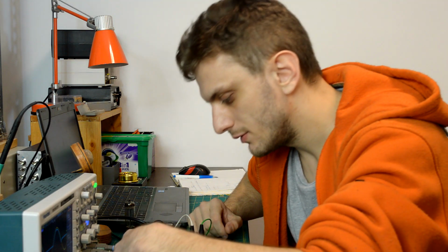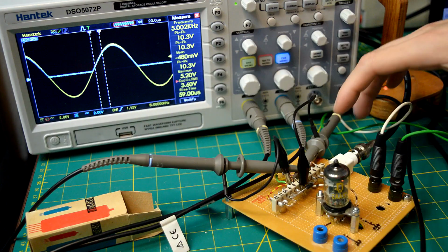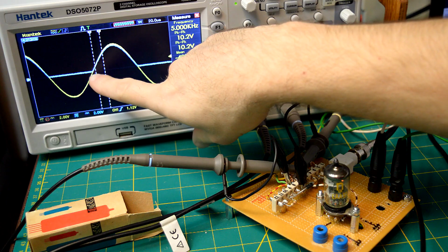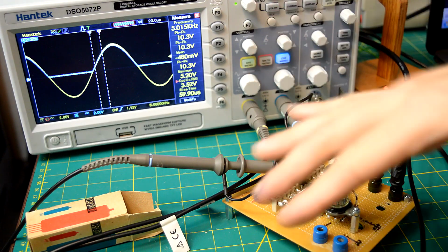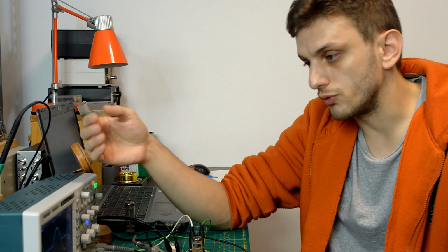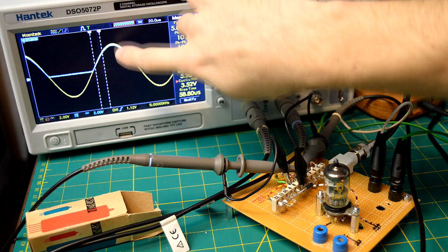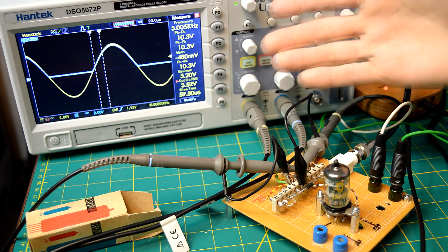Now if we move to the vacuum tube diode, we see that our waveform is a bit different this time. The vacuum tube diode starts conducting instantly, so once the voltage turns positive, it will conduct. There's no threshold voltage needed to get it to conduct. We still see that there's a bit of voltage difference between the input and the output signal, and this is because of the voltage drop on the diode. Vacuum tube diodes are notorious for having quite large voltage drops on them, especially at high currents. And for vacuum tubes, high current means 10 milliamps.